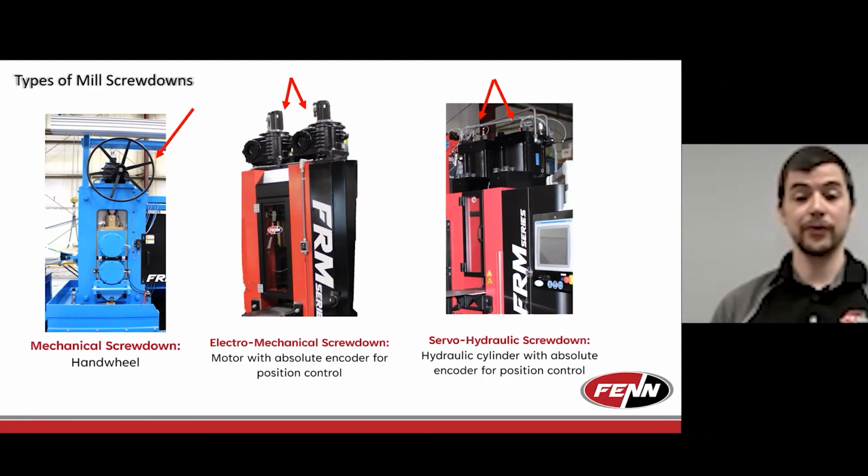So really, when it comes to electromechanical versus hydraulic, electromechanical is easier from a setup standpoint. It's easier from a maintenance standpoint. It's lower cost. So my rule of thumb is I default to electromechanical unless the application demands that we need to make large motions quickly, drive under load, and hold position. And for those applications where that's so critical, that's when hydraulics come into play. And that's when you see them much more common.